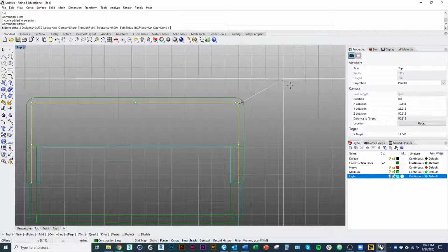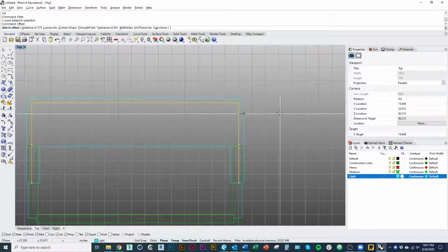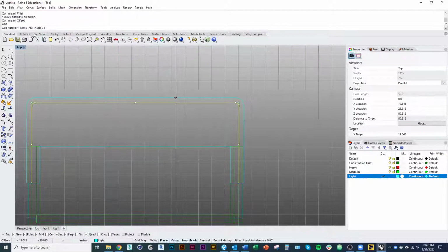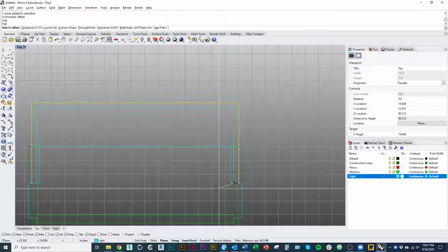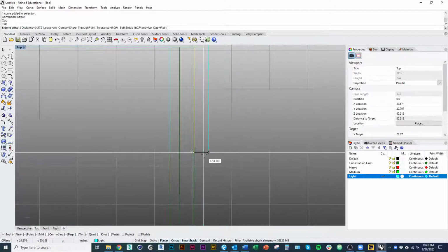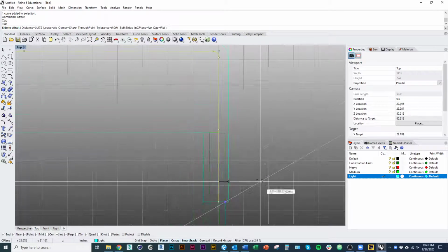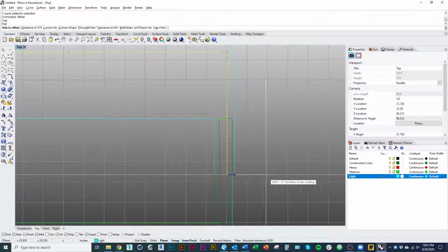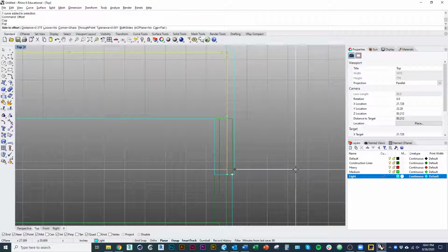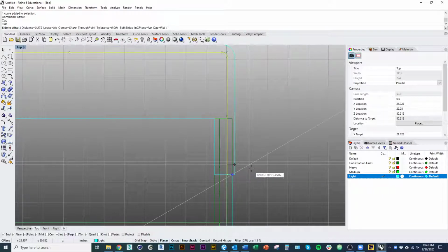And the other thing that I'm going to do now, apart from changing my current layer, is I'm going to choose this option called cap. And what cap will do, if I click on it, it'll give me a few options, and I can click on this one, flat. If you look at the end of the line, it's kind of hard to tell, but it's connecting the original line with the offset line. And that's good because it saves us the trouble of making one outline from the original line and the offset line. Automatically connects them, creates a closed outline. So that's the option we'll use to create a closed outline from the handle. And then I'll set my distance, so I'll type in 1/8.